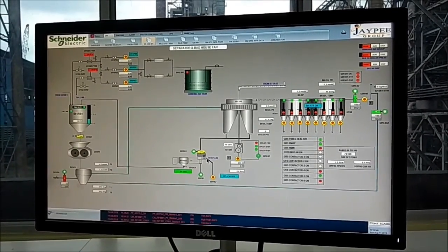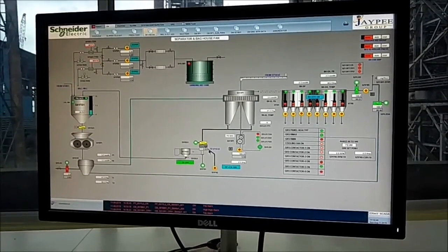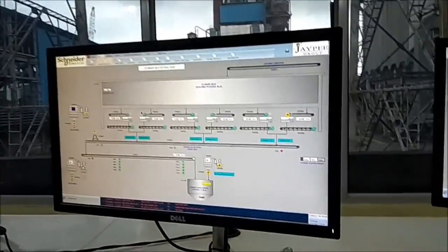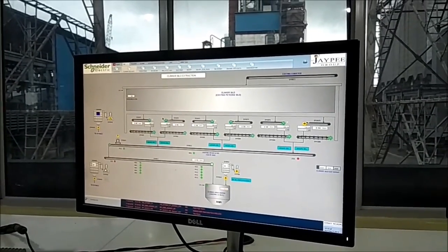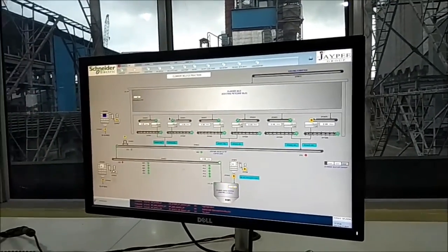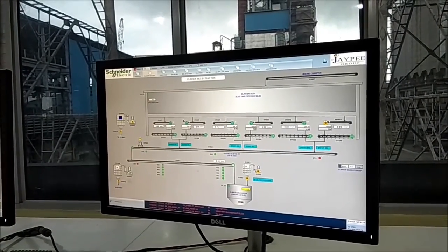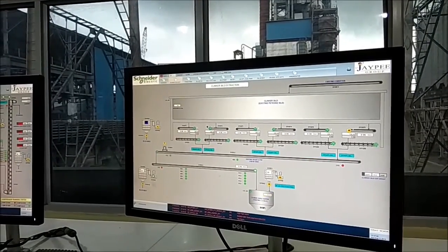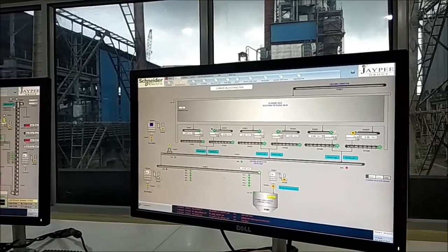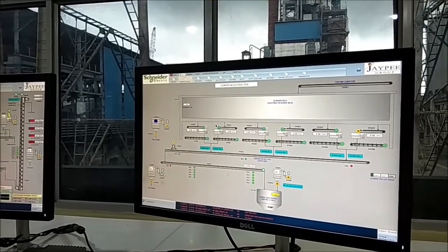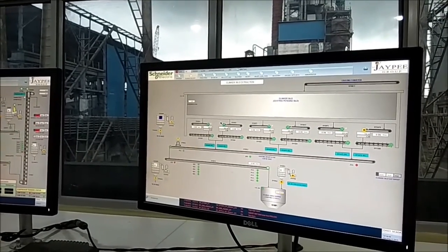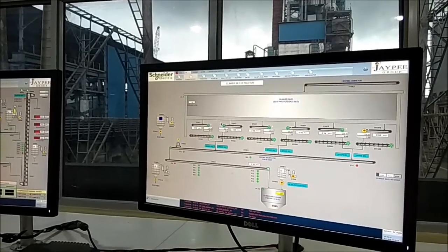Then calcination, then burning zone, then cooling, then there's a cooler, and then in the cooling, the clinker, which is around 1450 degrees Celsius, becomes liquid form because of the high temperature. Then they start rotating and they become round nodules. And the cooler, we cool it, and then there is a crusher, it crushes it back, and then it converts into powder.